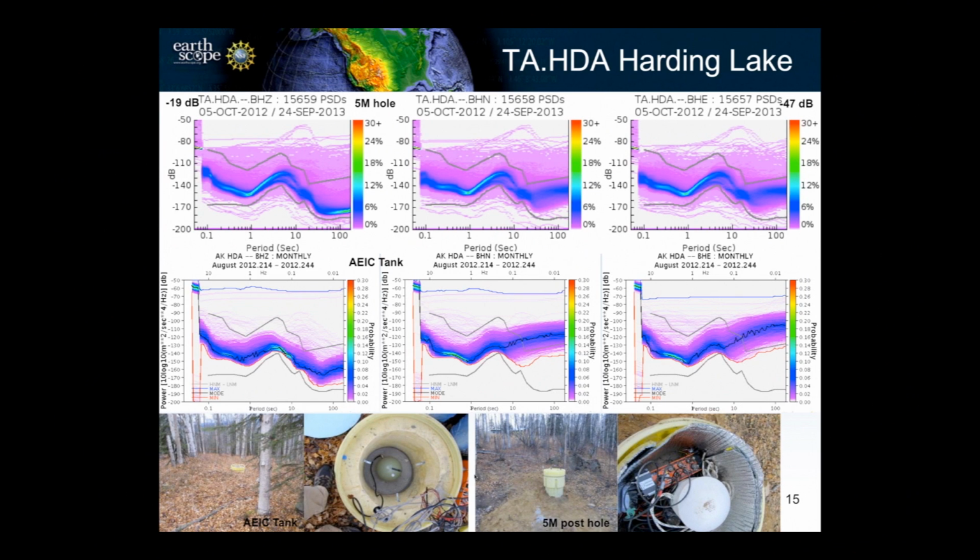And putting the seismometer deeper and getting more insulation and less of an influence from noise either induced by wind in trees or just other cultural noise, as you can see here, has really changed the performance of the long period response. So you're at about 100 seconds here on HDA, and you can see that formerly before it was above the high noise floor.